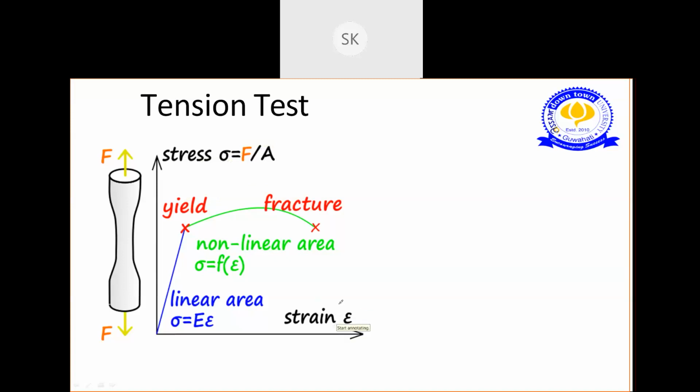To know the material behavior, we discuss it in terms of a graph, the stress strain graph, and we plot stress and strain instead of force and change in length. Why do we do this? It allows for the removal of geometry from the problem and allows the results to be used for different geometrical shapes of the same material.